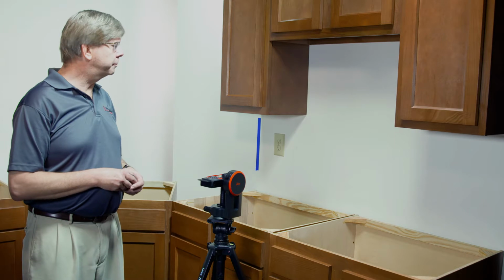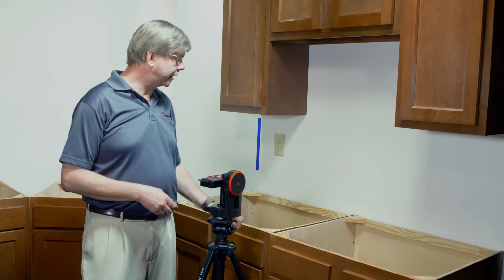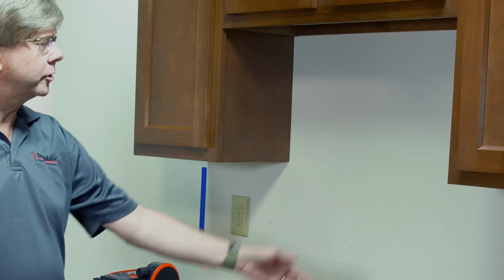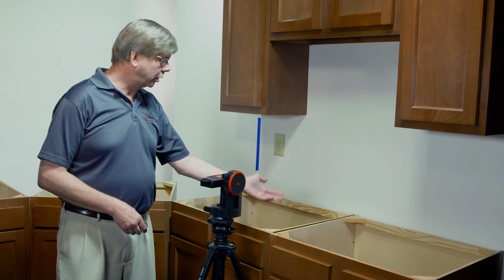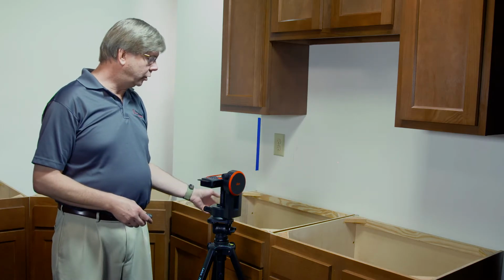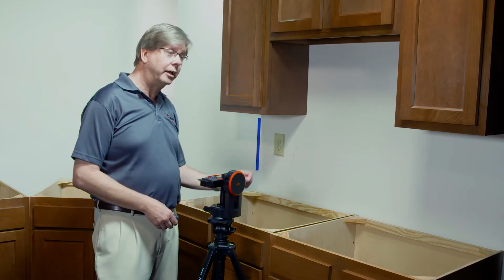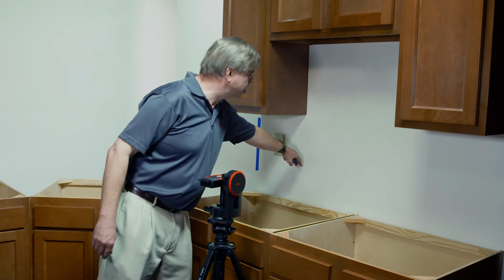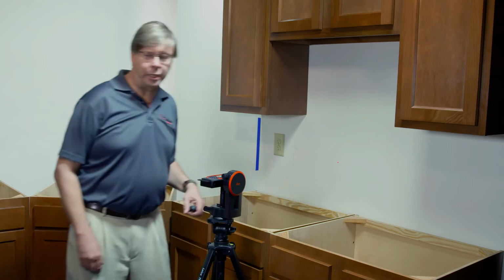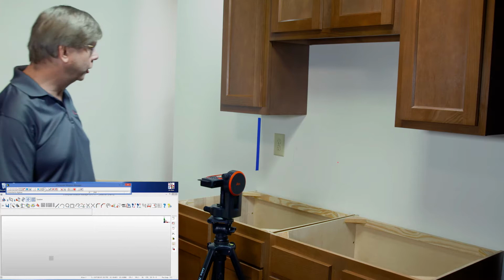Okay, we're back, and we're going to now do our full height splash. You'll notice in terms of the laser position, it's still on the tripod. It's about halfway between the top of the lowers and the bottom of the uppers, so that we'll be able to get all of our measurements. When needed, you can also take the laser off of the tripod, and it can be just laying by itself on a small foot. So right now we need to establish this back wall as our XY coordinate system. So we're going to select the XY icon and take 3 points.